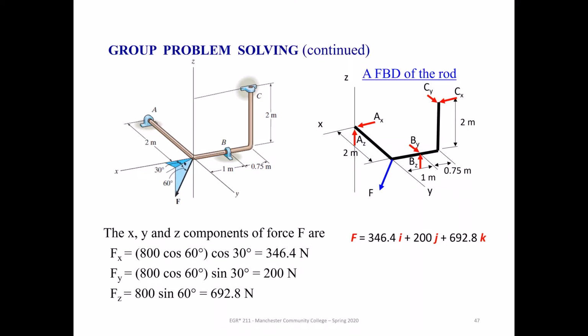If you wanted to think about this as some vector F prime right here, and you have this 60 degrees. To figure out this component, which is your z component of the force, it's just going to be that 60-degree angle relative to the xy plane, and it's going to be the sine times that. That's what this is right here, times F, which was given as 800 newtons. Then you use the cosine of 60 degrees times this force vector 800, which gives you this. That is the component, this vector right here.